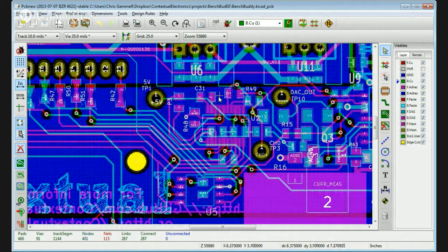So that's basically just a high frequency choke. Usually it's 100 megahertz and above, but it's just good to have a blocking inductor there for high frequency noise between the digital and analog realms. A digital signal going out might only be at 4 megahertz or 2 megahertz, but if you look at all of the harmonic frequencies and the fast rising edges, that starts to get up above 100 megahertz sometimes, even in the tail. So that's basically what you're trying to get rid of there.